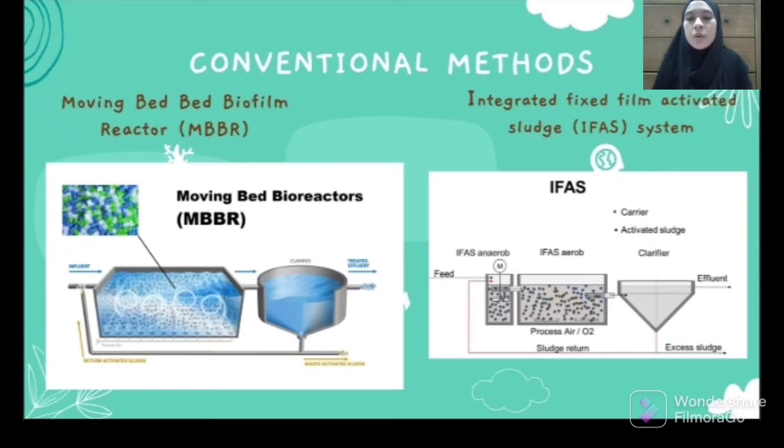Biological treatment with aerobic activated sludge has been used for well over a century. Biological treatment procedures such as the moving bed biofilm reactor (MBBR) and the integrated fixed-film activated sludge (IFAS) system are biological treatment processes in wastewater treatment that offer compact treatment plant designs to overcome the disadvantages of the CAS process and generate higher quality effluents in a smaller footprint.